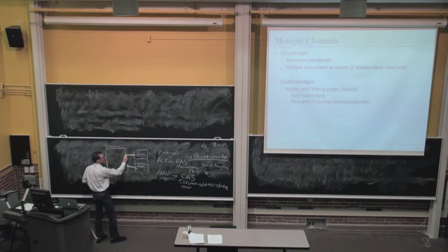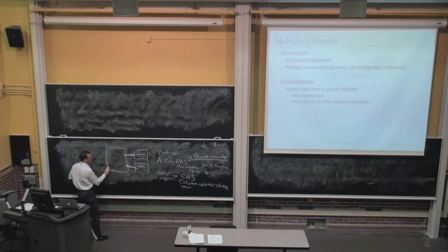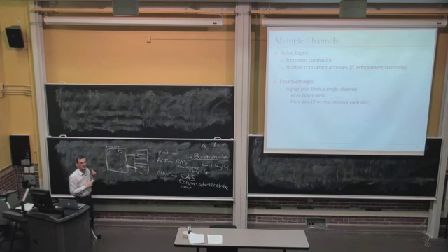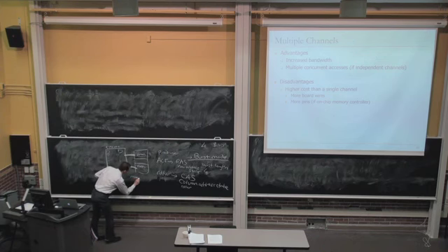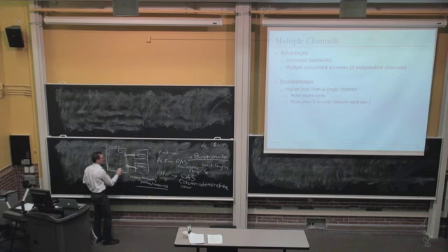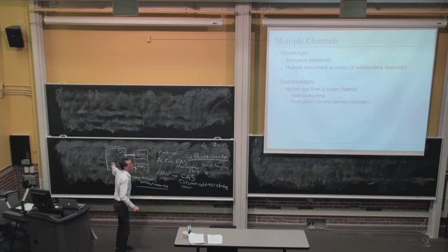These require pins out of the CPU chip, and as you add more cores, they require more bandwidth, which means that at some point, these pins saturate with the data they transfer, and putting more cores may not make more sense. Right? So this is called the memory bandwidth problem. It's the same thing that had been experienced with vector processors, right? But it's perhaps more severe because now you can actually generate many more accesses here, because the processors are much faster also.